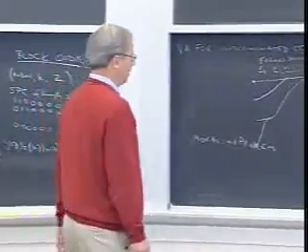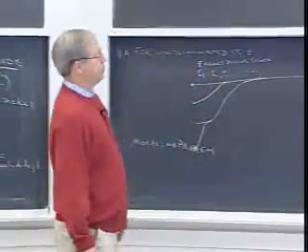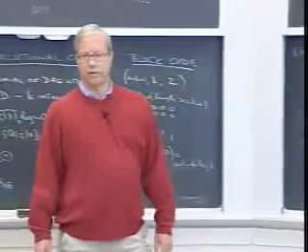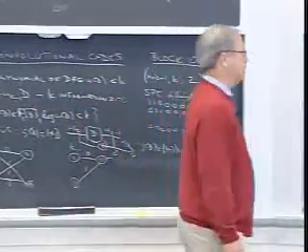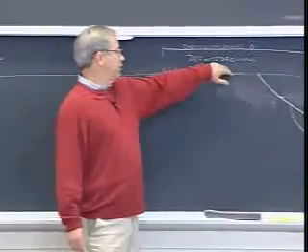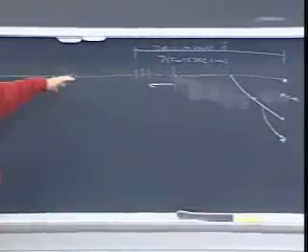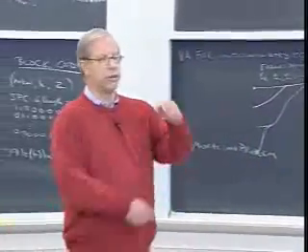Keep them within running time. So we don't need to terminate convolutional codes in order to run the Viterbi algorithm. We just let it self-synchronize, and we make decisions with some decision delay. And the additional problems that we have are very, very small if we do this. There are no additional problems.